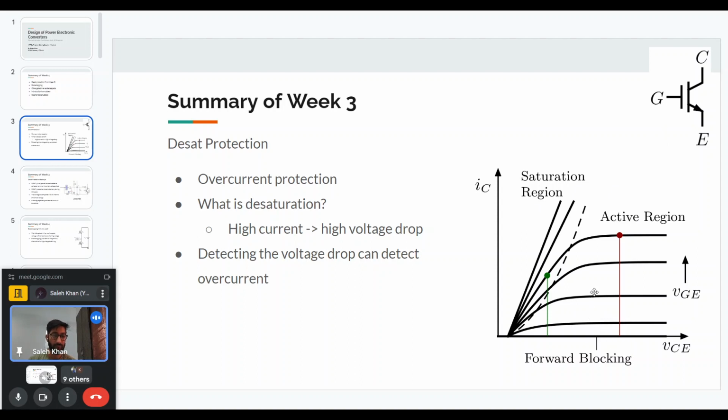So we will do the necessary measures to stop the fault or avoid damaging the switch, whether we turn off the switch or turn off some other aspects, some input voltage or something else. But mainly, we're using DSAT protection. When this threshold is reached, we will turn off the gate pulses to the device so that the switch becomes off, and usually the short circuit is avoided.